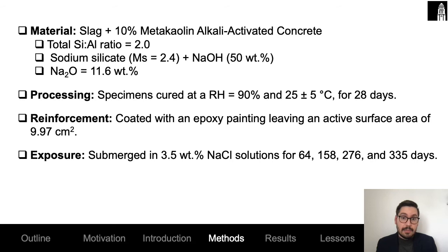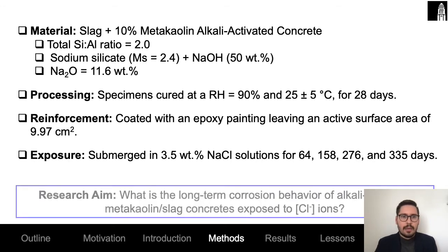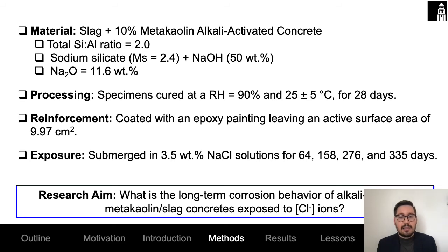All the specimens were then immersed in 3.5 weight percent sodium chloride solution for a total duration of 335 days, and they were tested at 64, 158, 276, and 335 days. The research question that this project aims to answer is: what is the long-term corrosion behavior of these alkali-activated concrete materials when exposed to chloride ions?